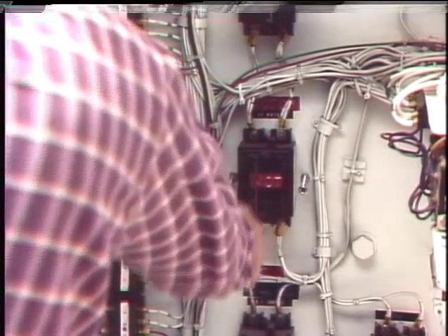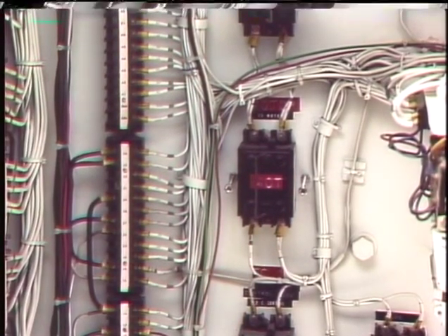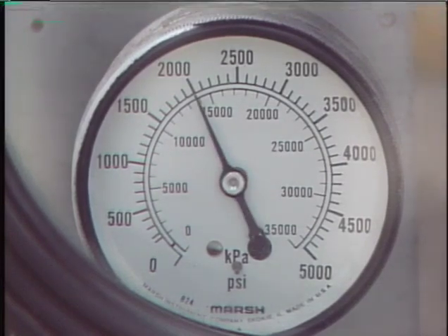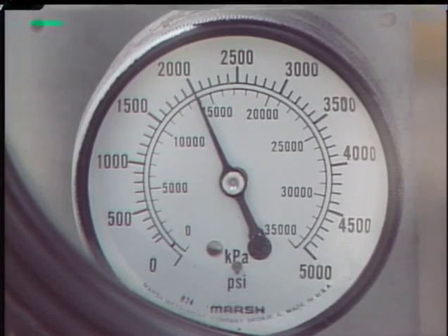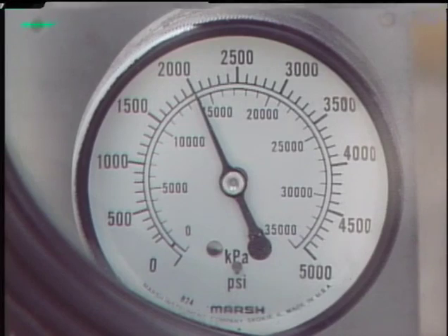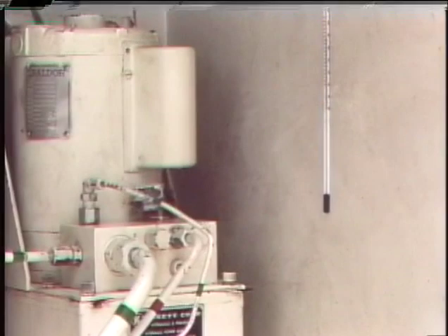Now, to determine the pre-charge, the first step is to energize the motor so that it pumps fluid into the accumulator. System pressure will increase rapidly until it reaches the pre-charge pressure. Then any additional pumping will only slowly raise the pressure. When pressure stops increasing rapidly, the motor is de-energized and the pressure is noted. The ambient temperature is also noted.